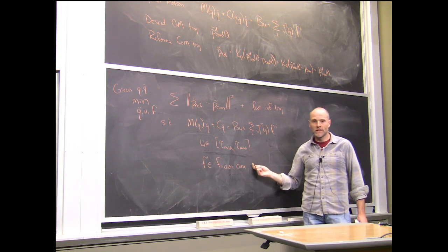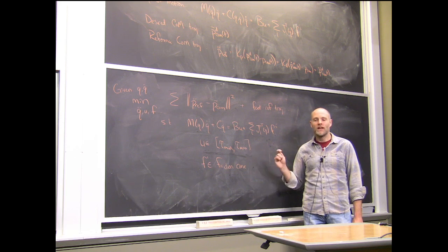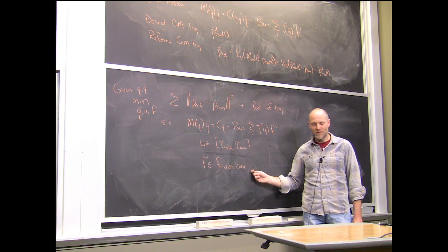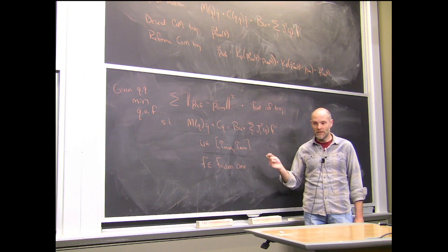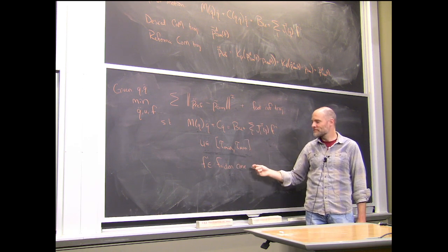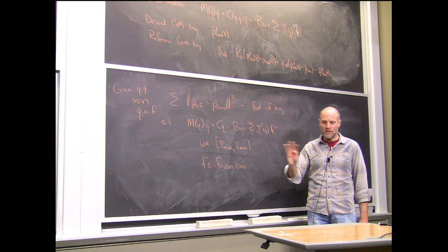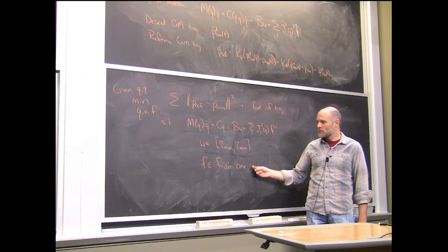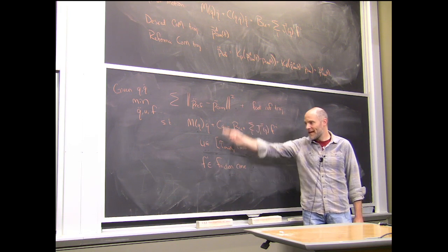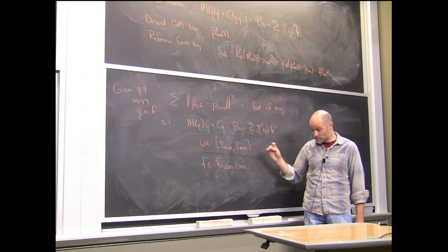We were solving this with Gurobi at about 300 hertz. Actually, that's not true. With Gurobi we were getting close to 300 hertz, but then we wrote a customized solver that solved this most of the time, way faster actually. We called it FastQP, and it just used a bunch of heuristics. It wasn't a complete QP solver, but it took the last solution and tried the same active set constraints.